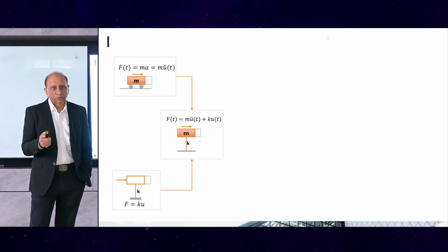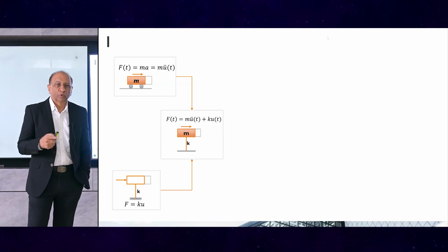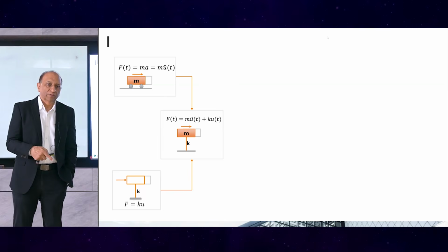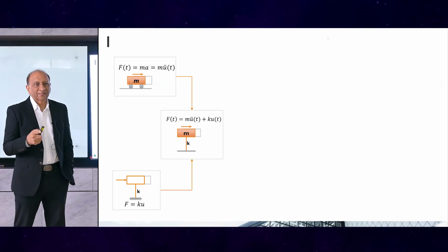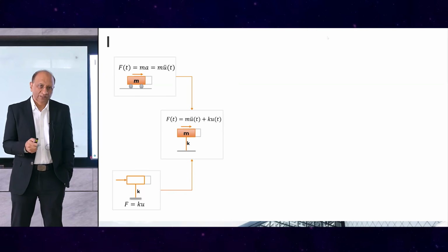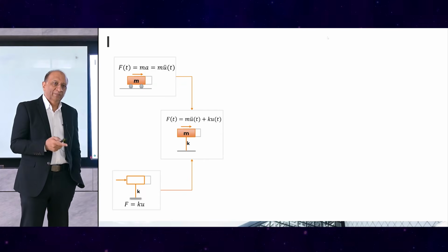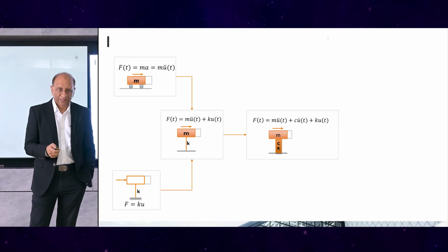And then when you combine the two together, you got the first equilibrium equation of moving bodies, but restrained moving bodies. So stiffness, mass, and force were then related in that way, varying with time, of course, because we're looking at things which vary with time, especially when you're having acceleration in a mass.